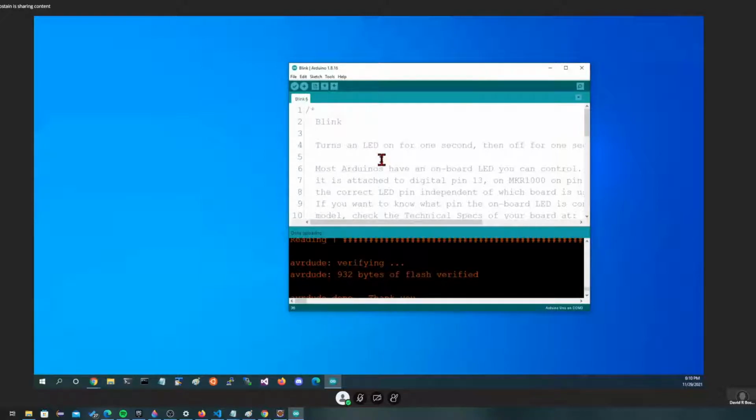Now, one of the things that happens in the Arduino environment, because it's kind of a watered down version of C++, is they arrange the hardware to have certain non-default conditions. So one of the things we're going to do when we initialize our assembly language is undo all of the things they did to make it Arduino friendly.